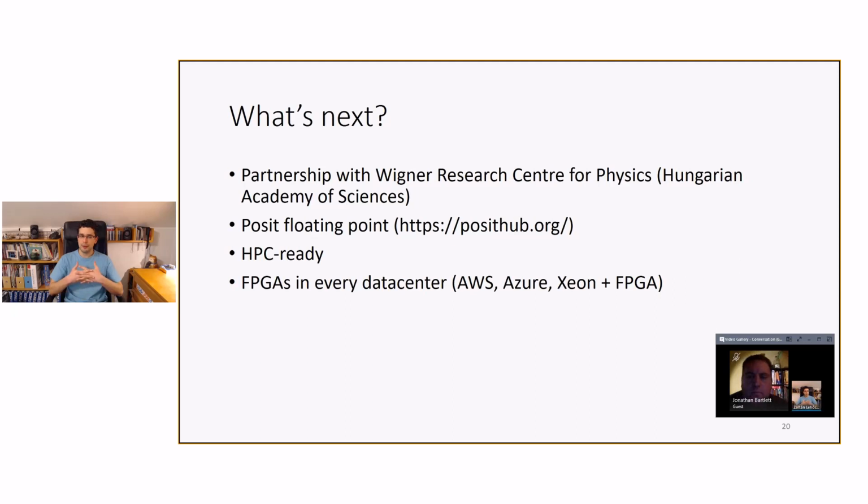And what we want to see with them is how Hastlayer can help scientific computations. We actually have an example among the examples that are also on GitHub, which is an algorithm we got from them. It's more power efficient than on a CPU, but not yet faster. And the reason is also that our FPGA is too small currently to fit enough parallel executors of that more complex program.